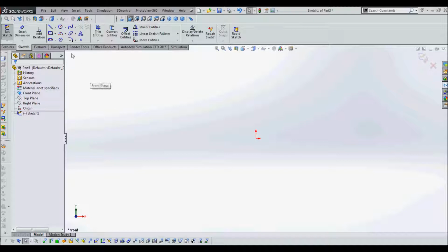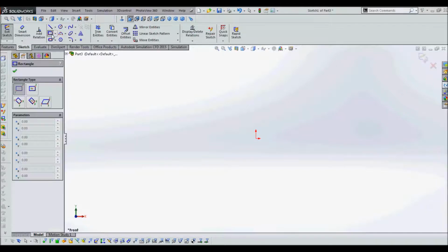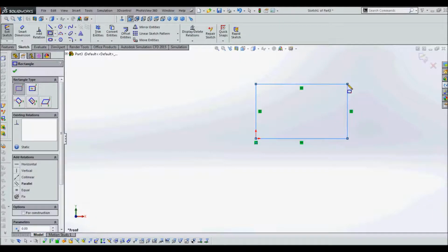So to begin here, we're going to go up and we are going to select the corner rectangle command. We'll click on that. And now, moving over here, you'll see there's a little icon that shows that we have opened the rectangle command, and we'll click one point at the origin. We'll then drag and click once again to set the other point of the rectangle. So at this point we're drawing a side view of what's going to become the cannon base.